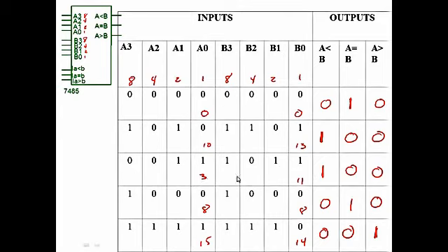So we're just looking at numerically which one is either greater than or equal to the other one. That's all we're doing. Now, like I said, these inputs are for if you want to tie in another chip. Let's say we have another one of these comparators and we have our 3 outputs. Well, those 3 outputs are going to tie up to these.